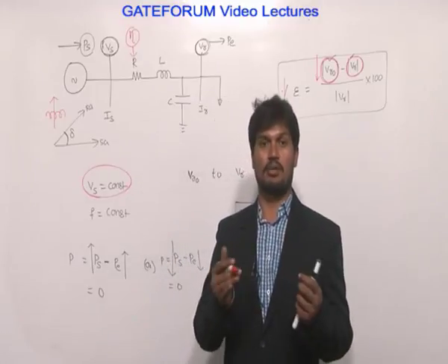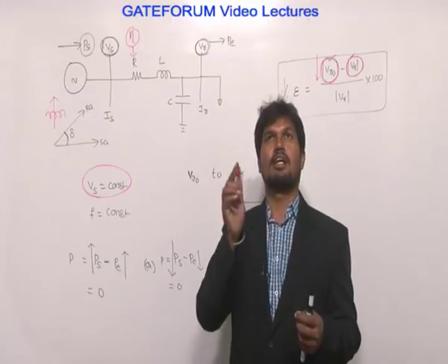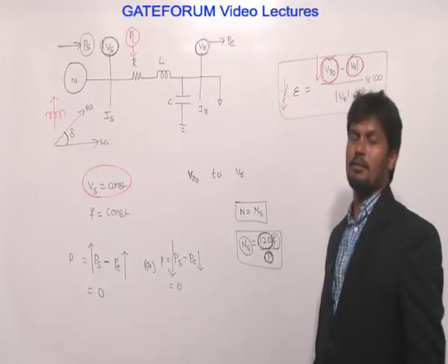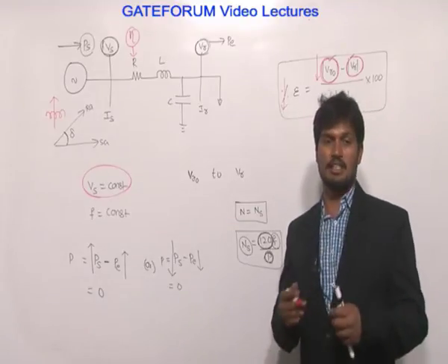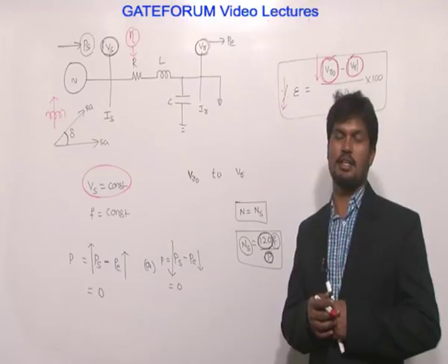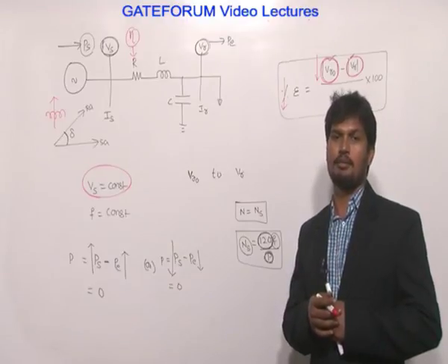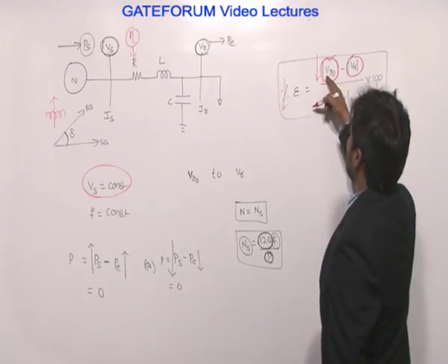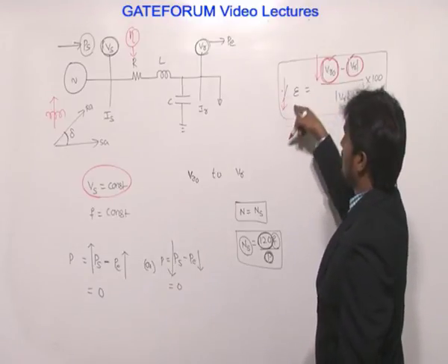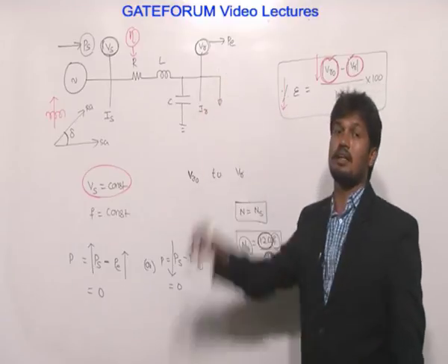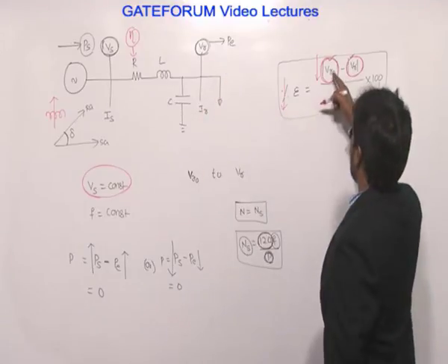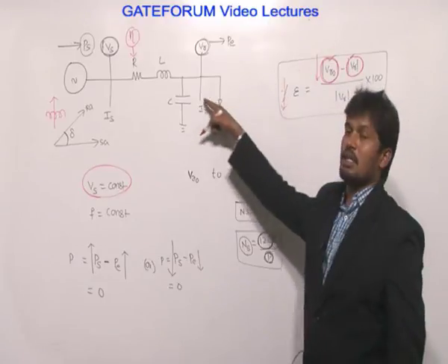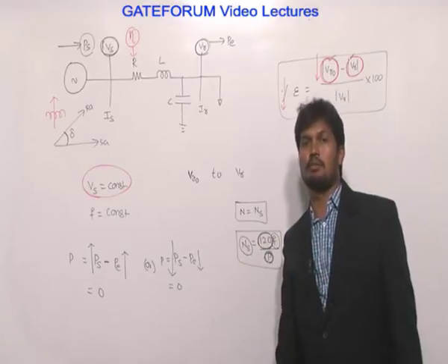If change of voltage is more, constantly in our homes voltage will fluctuate, and definitely electrical equipments will be damaged. Then we must purchase all electrical equipments again, out of next month's salary. I hope you understand: change of voltage from no load to full load is less, so the regulation is also less, meaning a better voltage at the load point. If the change is more, regulation is also more, and there is a very poor voltage at the load point.